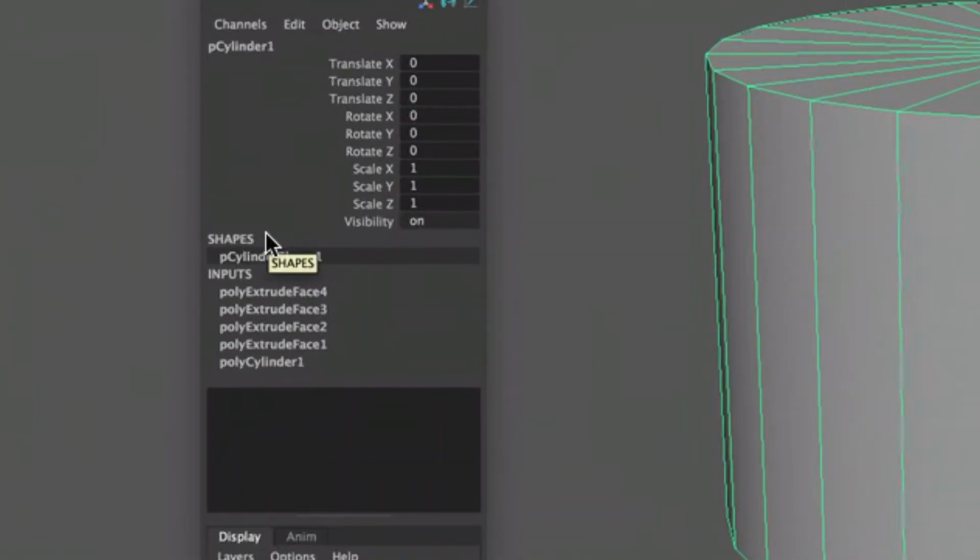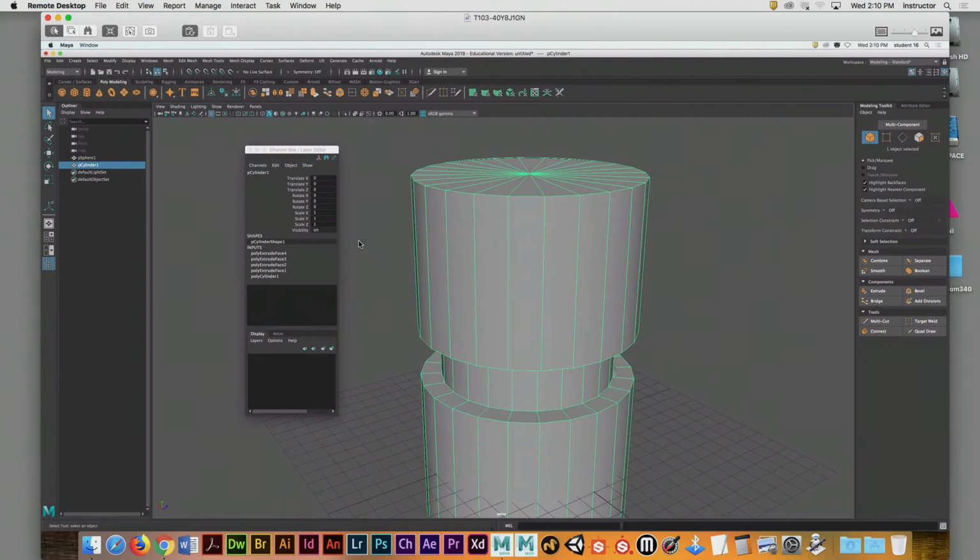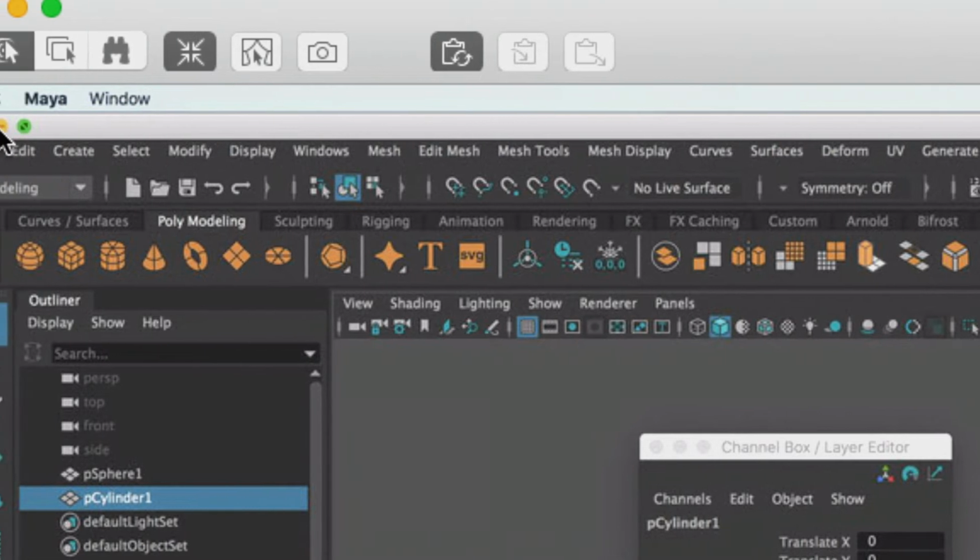If you've been modeling for a while and you notice all of a sudden that Maya is starting to bog down and get really clunky, the performance just evaporates. Select the object that you're working with and look at its object history. I forgot to delete my history a couple nights ago, and I had probably 200 different input nodes on one object, which was leading Maya to basically come to a complete crawl. So we want to delete our history from time to time when we get to major destructive edits or to a point in the modeling process that we're okay moving on from our past. Deleting our history is really easy, and it can be done in a couple different places.